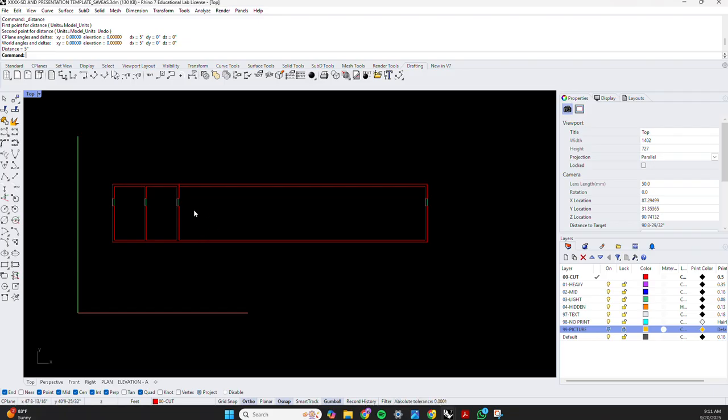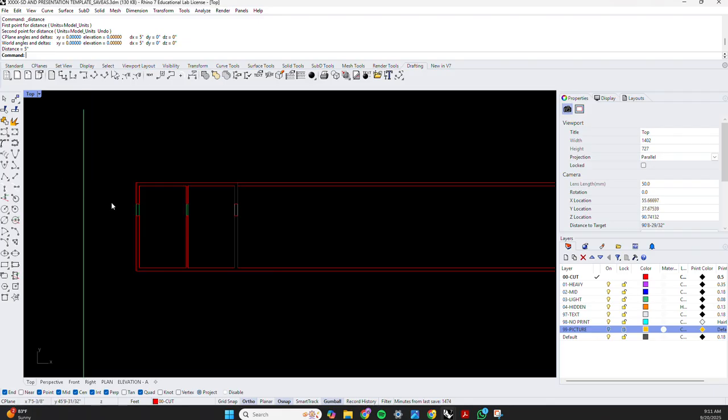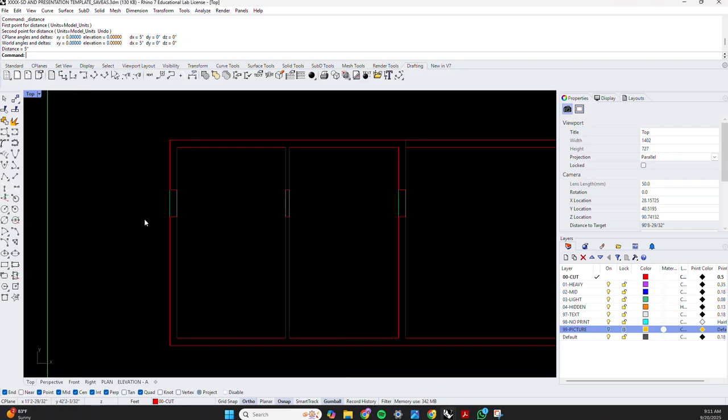However, assume that we want to do other things to this. Say we want to put a hatch in. By having this be precise and rigorous, it means that if you were to put a hatch on this section, you could just rotate that down and you would know that it would exactly fill the wall on this side. If it was not 90 degrees and you put a black hatch, there'd probably be a little white sliver open and you would have to separately drag that to the corner. It would be a lot more time consuming.